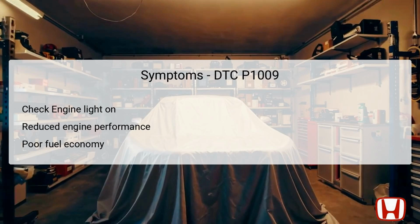The detection of DTC P1009 typically exhibits several symptoms that can alert the driver to an underlying issue. The most apparent sign is the illumination of the check engine light, indicating that there's a fault code present. Following this warning, reduced engine performance may be noticeable. The vehicle might lack power or responsiveness due to improper timing adjustments.